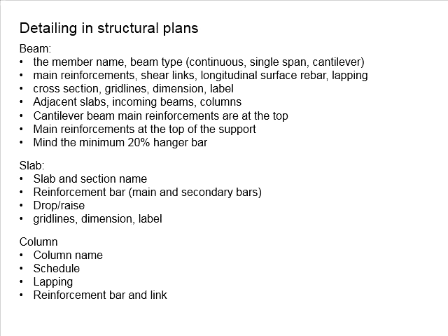You will use the structural key plan for your analysis and design, and then the design outcomes are to be illustrated in the detailings of each member. When you construct the detailings of each member, you need to make sure the information given in the detailing is in line with what is given in the structural key plans, particularly the names of the members, the conditions of the members, the dimensions, the respective grid line, and so on.